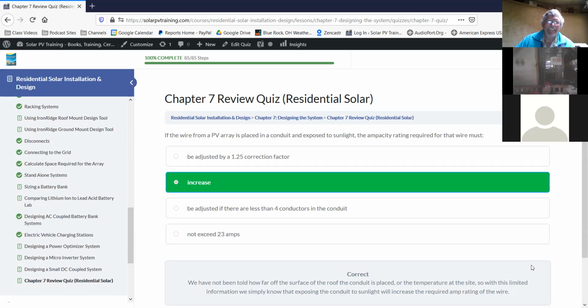So that's where the new temperature rating came from. Faulty science for the first one. They had the conduit capped off, and they did the temperature rating, but they were looking at solar ovens because there's no circulation. That's what happened. So they redid it without capped off conduits and go, oh, wait a second.